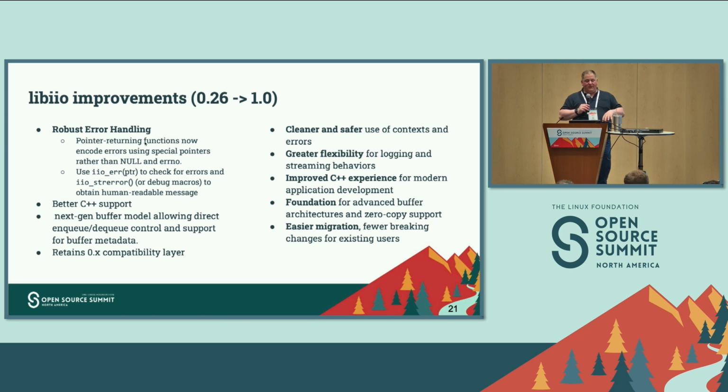So in libIIO 1.0, we changed that paradigm, made it a little different to do, but now it's really a streaming data buffering model so that we can actually consume 100% of the maximum bandwidth of these transport mechanisms. Because you say, just send me data, and it starts sending data until you tell it to stop.